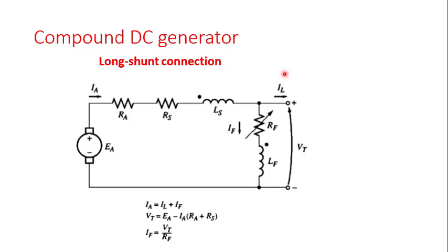It's just like a river that splits. If you want to get the amount coming, then you have to look at the two splits and add them, then we get the amount of current, water, that got to the branch or the junction. So that is it. That's according to Kirchhoff's current law. We are just applying Kirchhoff's current law, Kirchhoff's voltage law, and then Ohm's law. Those are all the three laws we are using in this circuit analysis. So you have to make sure that you understand this principle: the current law, the voltage law, the KVL or the KCL, and then Ohm's law. That's all that we are just applying. So take note of that.